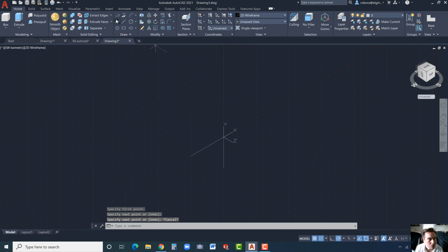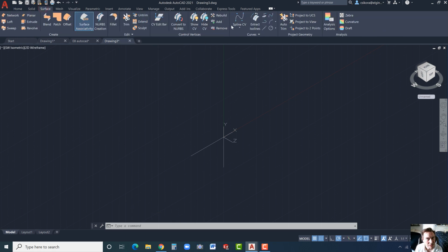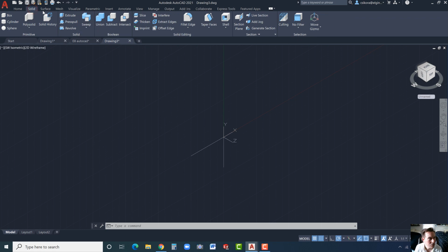Now we're going to use the spline tool here. Now if you go to surfacing, there is the CV spline, which is very nice, and it actually gives you control points. We're not going to use that. We're just going to use the basics right now, but know that later on we're going to design a bottle, and I think exercise 10, and we'll probably end up using that, which gives you fantastic control capabilities.